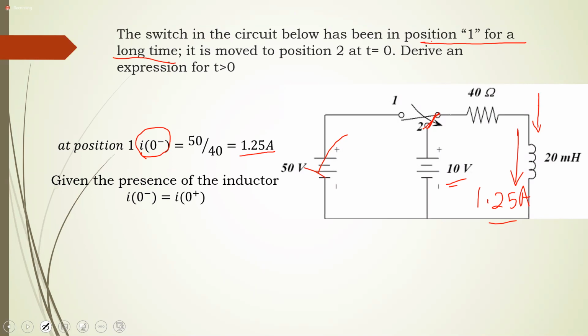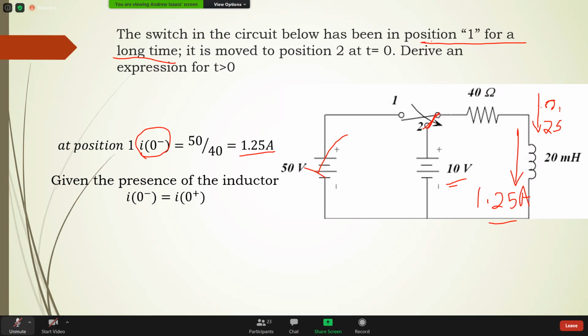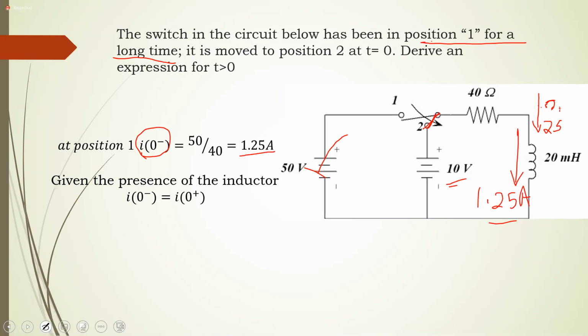It would be the 10 volts divided by 40 ohms. 40 ohms. Okay, so it's 10 over 40, which is 0.25 amperes. What is it? 0.25. Now, go back to the definitions that we just gave you. Yes? What did you say B was equal to?